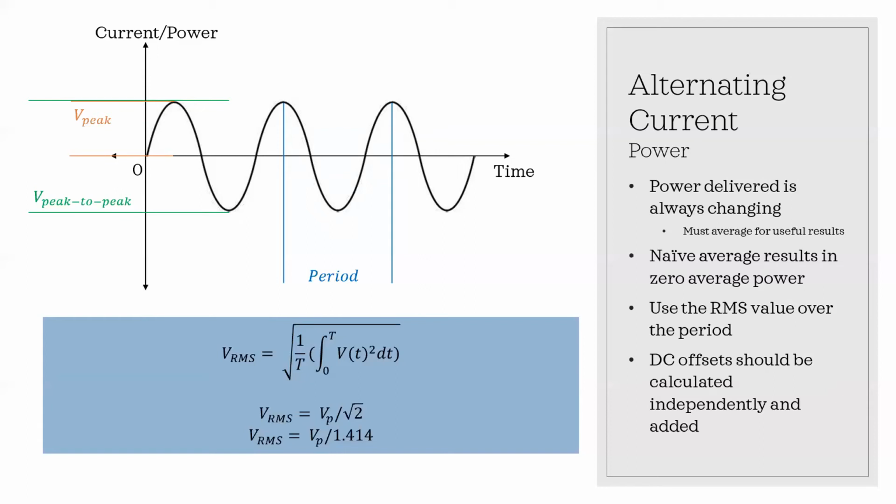And if everything is made out of sines and cosines anyway, then the RMS value is appropriate for each of those subparts, right? So that value applies to the created final wave as well. Right? So we use VRMS as V peak over the square root of 2 for every shape of wave. So we also sometimes will have a DC offset, which is just a straight line DC plus the sine wave, but we're going to calculate those separately, and then you add the DC and AC parts together at the end.